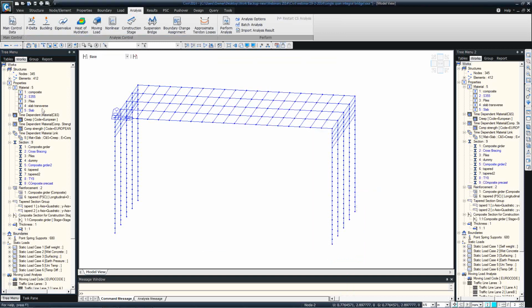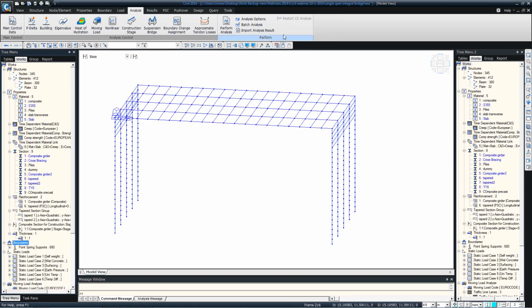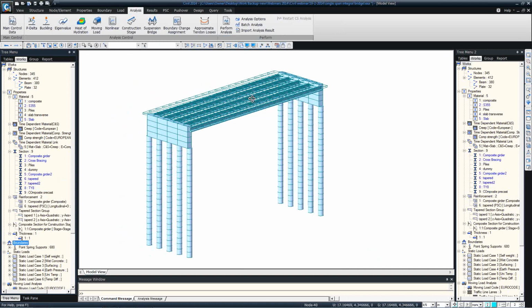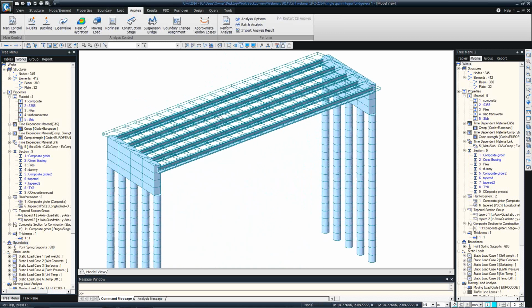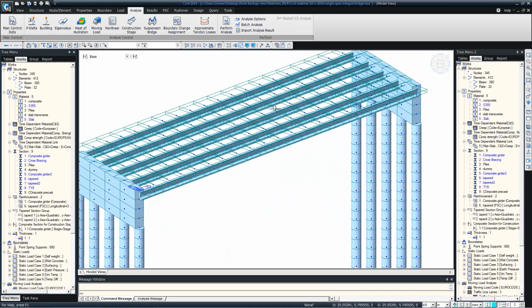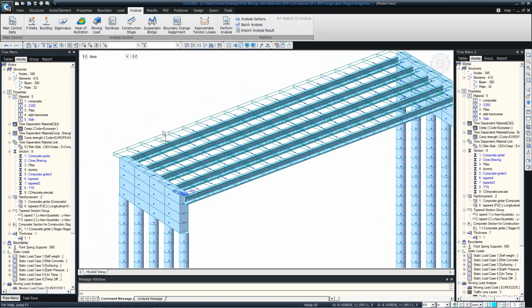So what I'm going to do is quickly drag and drop the composite precast section. You will see the dimensions are not exactly matching because the section size is too small, but anyway the objective of this exercise is to see how to quickly assign prestressed tendons, how the software can do the loss calculation for the tendons, and how you can get the ULS effects for dead loads and tendon prestress. So I will just activate the precast section.